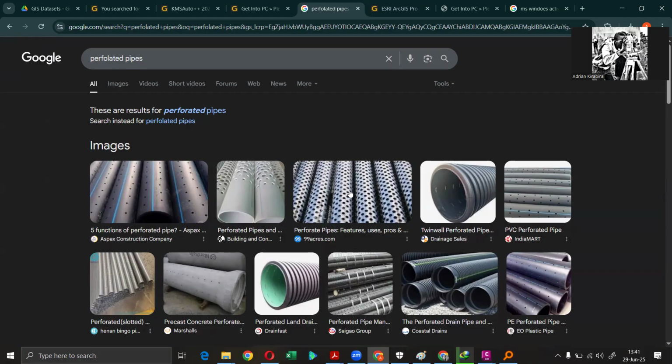Just praise the living. Yeah, and if you remember that section used to fail a lot. Yeah, it fails a lot, it floods a lot. Basically, this underground water goes down there. So yeah, even though you do the top part very well, on the other side the water is going to come. So what we did, you excavate, but again you cannot excavate all the way to the bottom. So in some cases you put rock fill.